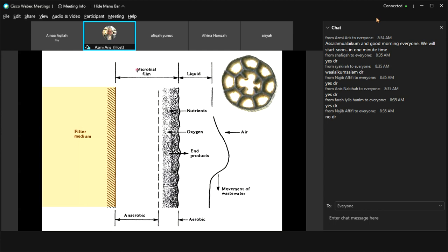And what we will do, we will pass our wastewater on the surface of this filter media. Okay, the wastewater will pass through this filter media, and with time, microorganism growing on the surface of this filter media. Okay, with time, initially it will be thin, and then it become thicker and become thicker and become thicker. However, the maximum thickness that we will find is maybe around a few millimeters. Okay, few millimeters. So it is not that thick, it is very thin actually.